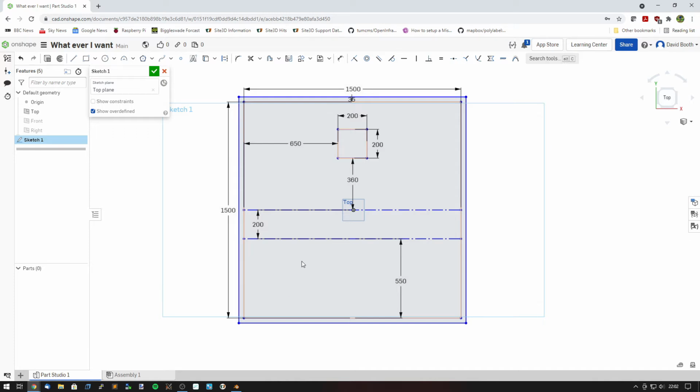Okay, so somewhat similarly, there's going to be a box down here again. So I'm going to drag it. If I start on the line, you see it selects the line, and this means it'll start snapped onto that line. So click here and go out. So I believe this is going to be approximately 500 mil by, I think, 325 is the size of that box. Obviously you can check that. It could actually be 225. So we can change this here. So 225.